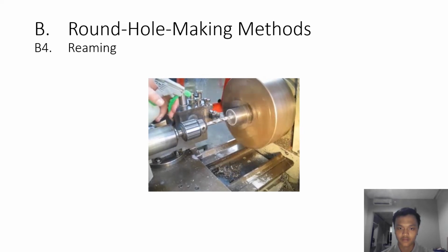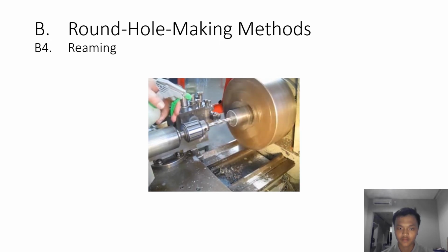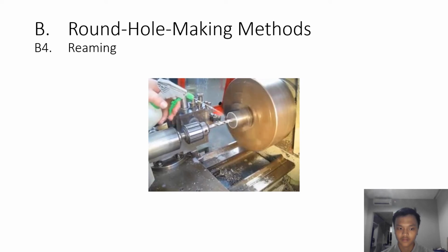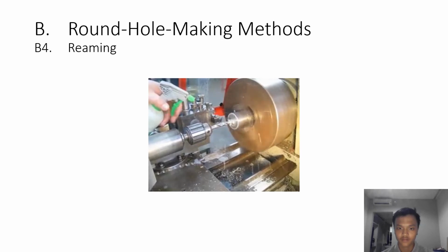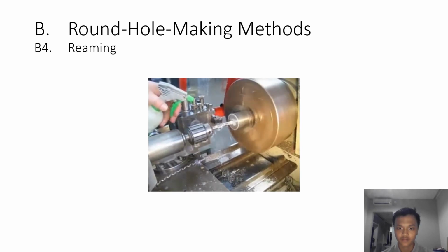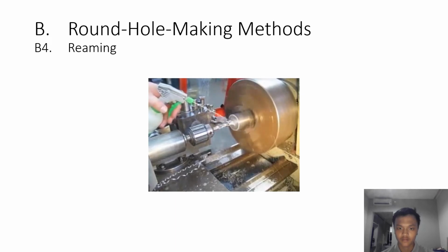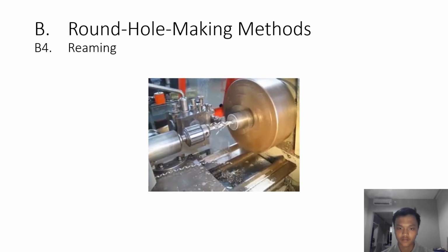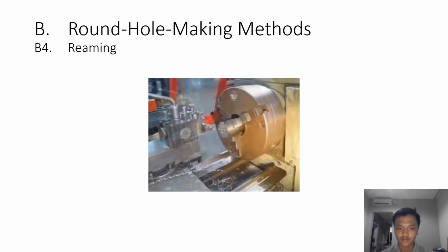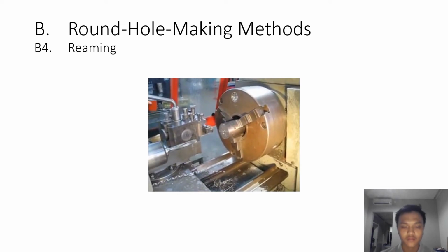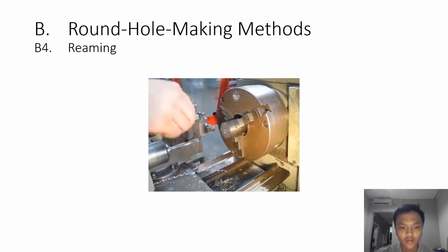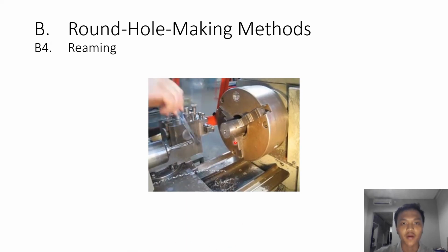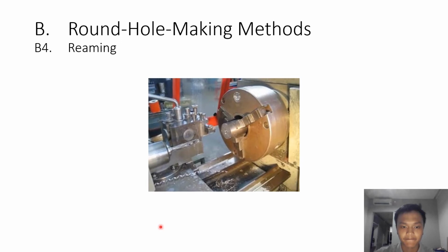Coolant should be delivered via the lathe's coolant hose. However, for the purpose of this instructional video, an alternate delivery method was used. When reaming, use a coolant with high lubricating properties. Now these are the reaming operation material requirements.